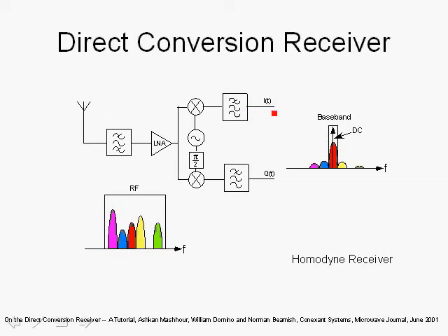The adjacent channel will be eliminated in the baseband digital signal processing stages using decimation filters, where we can afford higher digital complexity, and that's a trade-off between the analog baseband and the digital baseband signal processing, and we will discuss that in a whole separate topic.